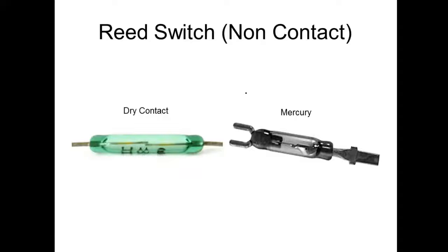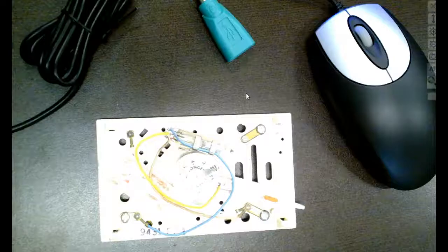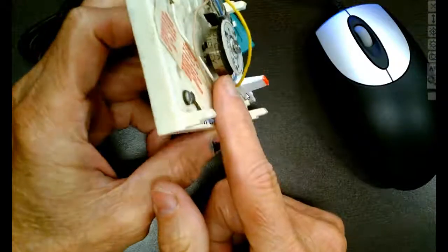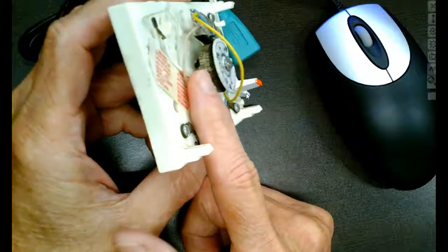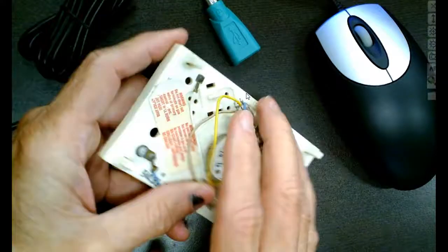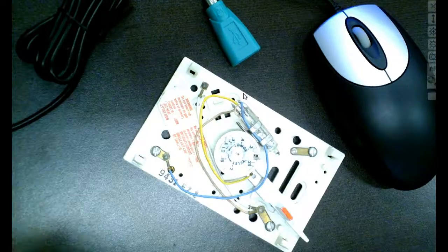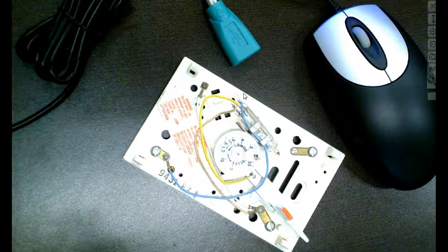So we used to use this. I was looking for my thermostat. So this is an old thermostat, and it's using a temperature sensor that we'll talk about later on. But it's using what we call a bimetallic strip or spring. And what the bimetallic spring does is two metals that are bonded together. And metals, depending on the metals, expand and contract with temperature at different rates.